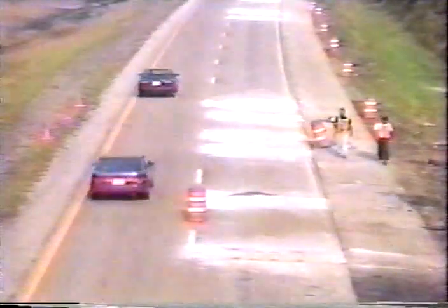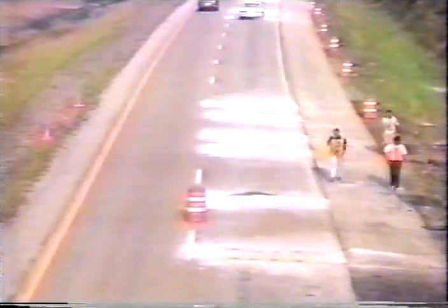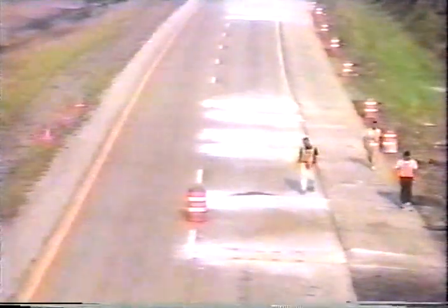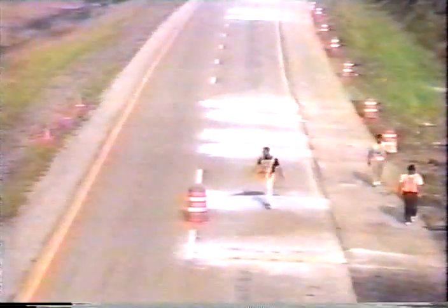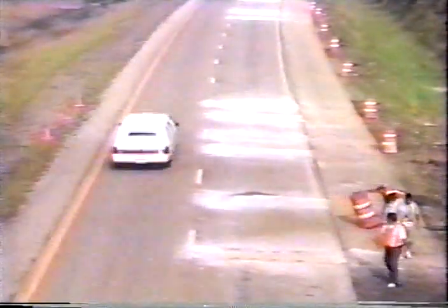Typically, the temperature near slab bottoms increases then decreases with the cement heat of hydration more slowly than does the temperature nearer the surface. Therefore, the concrete strength may vary at different elevations. When evaluating traffic opening times, it's recommended that the velocity be determined near slab bottoms, since critical load-induced flexural tensile stresses generally occur there. But when it's used as a quality assurance tool, velocity is typically determined at mid-depth.